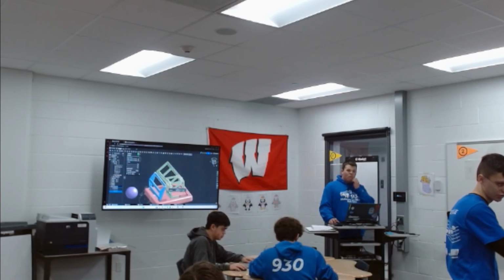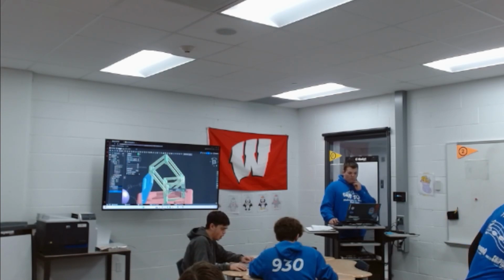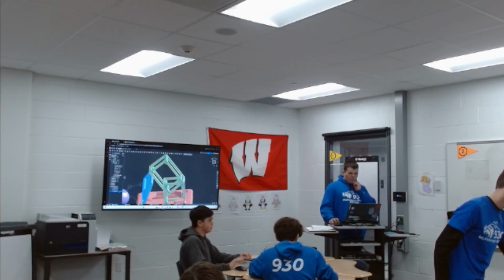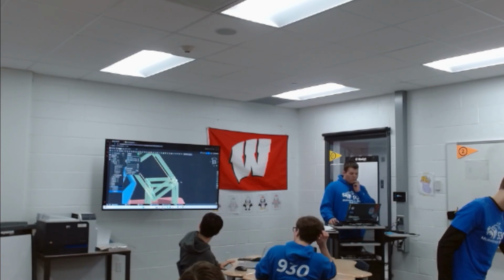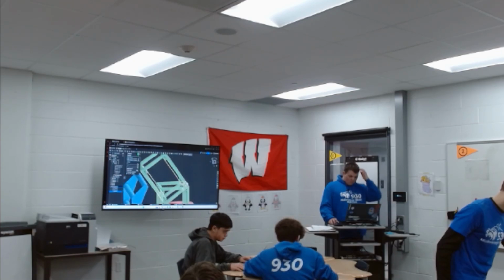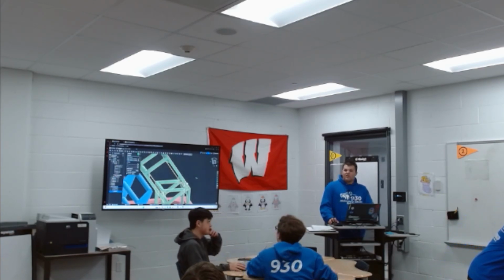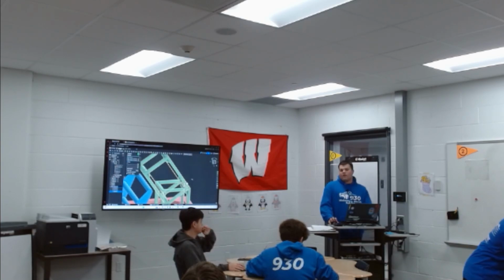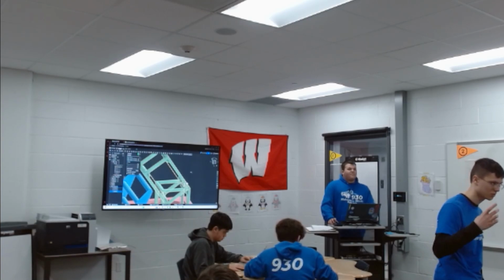You can also shift it manually if you want. So it looks like it is too high. Okay. So if you double click on your second fastening line down by the features, edit that fasten, double click on it. There you go. Now if you go to the offset option, you check that. You can then shift it. If you look there, it's 55 degrees in one direction, but you have to rotate about Z, not X. That's fine. So you want to shift the Y now. The height of the 2x1 base. That's what you want to do.